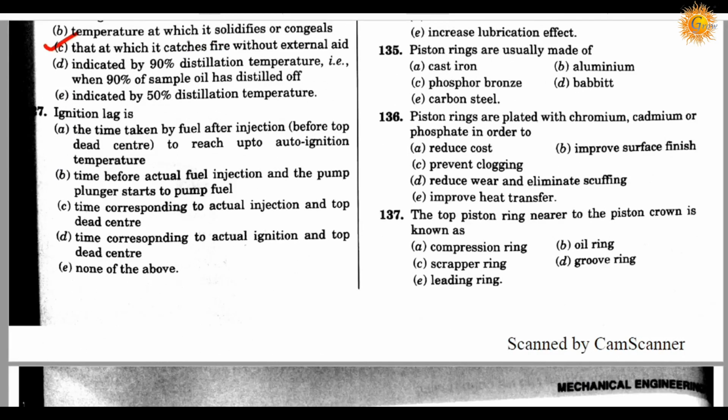Question number 127. Ignition lag is option A, time taken by fuel after injection before top dead center to reach auto ignition temperature. Option B, time before actual fuel injection and the pump plunger start to pump fuel.